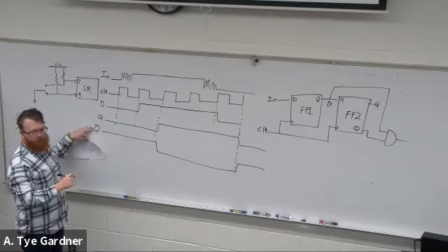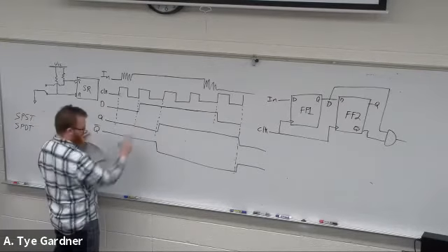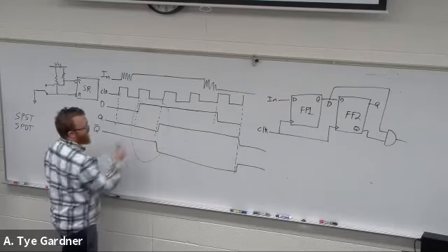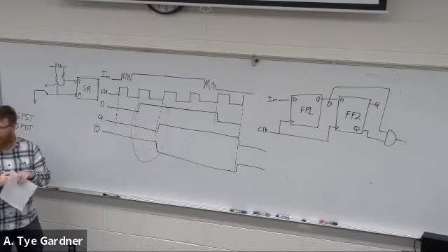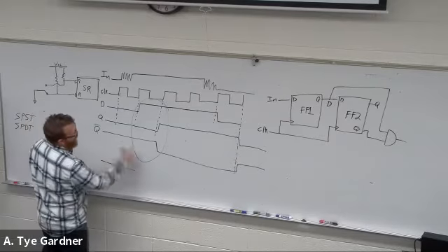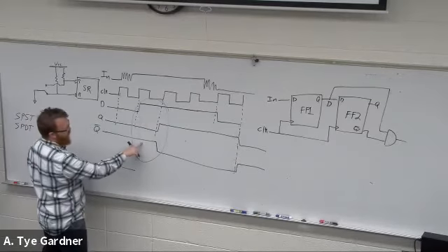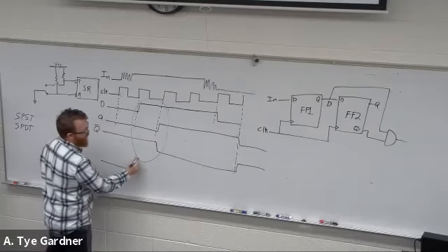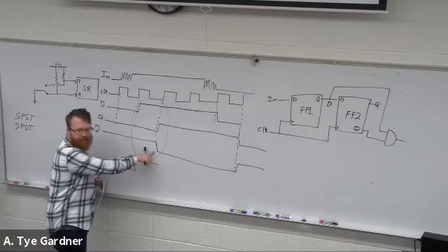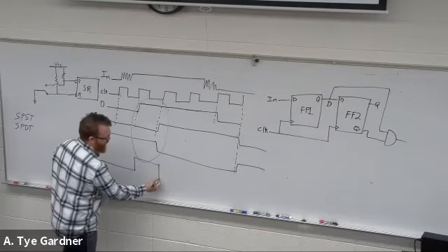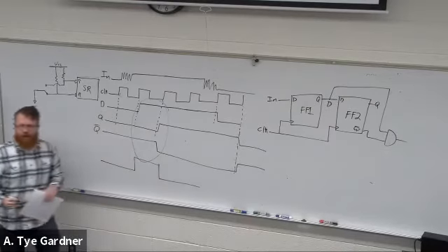Well, where is that true? Only right here. So the output ends up just going 0, 0, 0. This one rises. Not Q is still 1. So it pops up. Not Q drops to 0 a clock cycle late, right? The second flip-flop. So it drops back to 0 and on to 0.